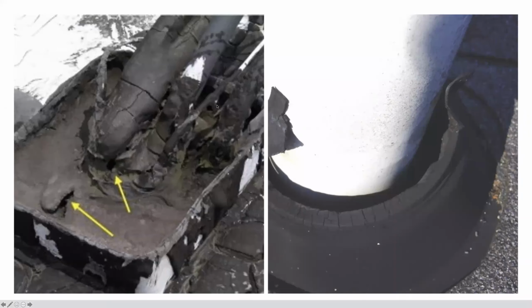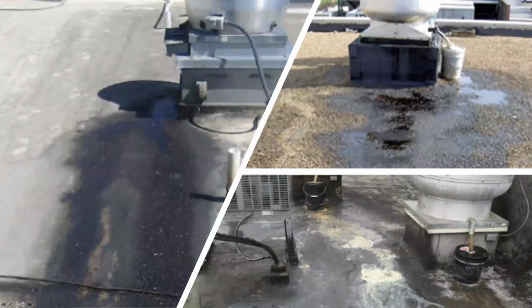Some other maintenance items, again, a closer look at one of these sealer pockets that's failing, and now you have points of entry to where this is going to take water in probably every time it rains. And old neoprene-based or EPDM-based flashings that are broken down from the UV need to just flat out be replaced. And again, we talked about the PVC membrane, which is really the right system for things like this, where you have grease. This is probably over restaurants, where they're not being maintained on a monthly, bi-monthly, or probably at least that frequency, and that starts to overflow, and this will prematurely degrade these materials, and you'll be replacing the roof much sooner than needed.